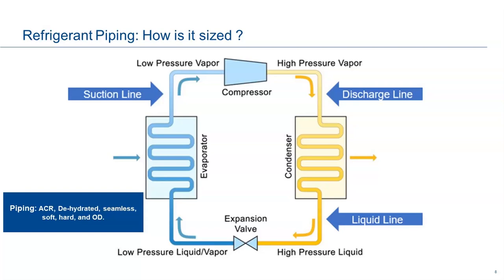Those are the two biggest factors. So if you ever wondered when you pulled that installation manual out why at a certain number of feet you might have to change the size of your refrigerant line, that's why. That's what the manufacturer, the person that designed that equipment, the OEM, is telling you, okay?